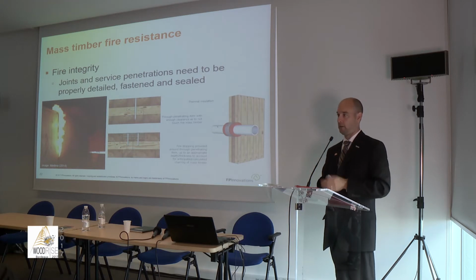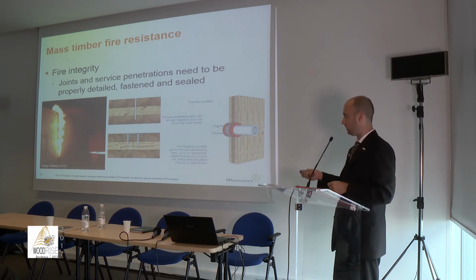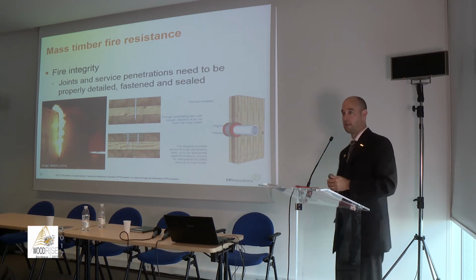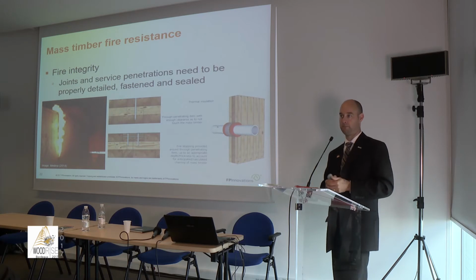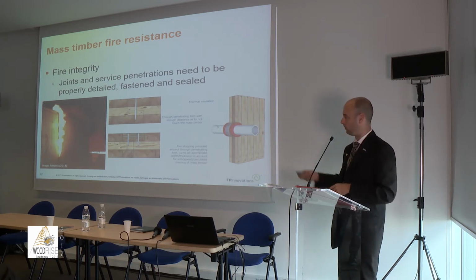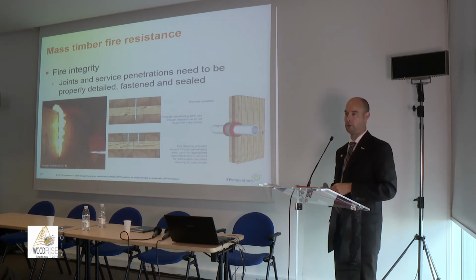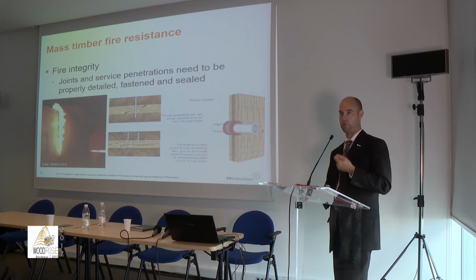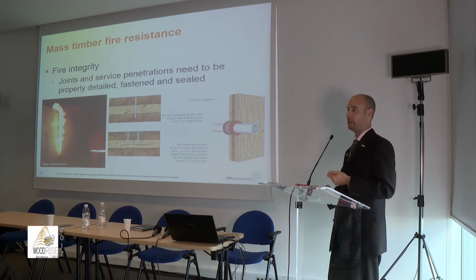Integrity. In Brad's talk, he mentioned the importance of sealing the joints in between the elements. This was one of the compartment tests done at Carleton University where the students forgot to put caulking between the CLT panels. So we ended up with flames occurring through the assembly very rapidly. So it's really important, if you want to fulfill that integrity criteria, that every joint is properly sealed.